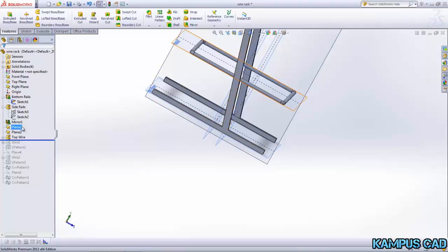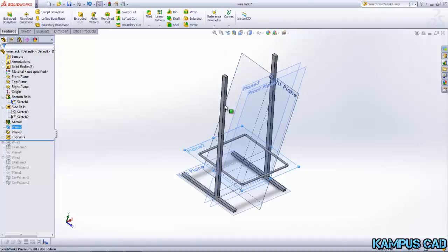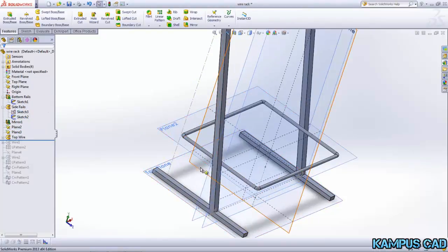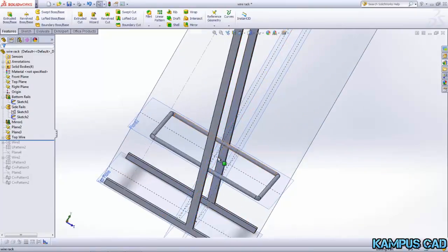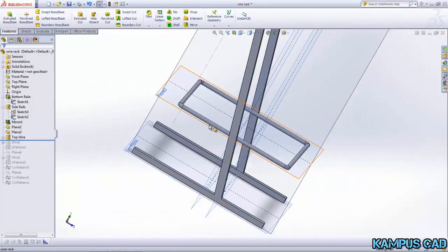And how I created those planes actually is I left behind some reference geometry. Let me make sure that trajectory is on. So my other sketch, I knew where I wanted to be at, so I left a point there. So I have this plane here, plane 2 and plane 3, intersecting that point. So instead of using a dimension to know how high up I wanted to go or how far over, I just left that point in my other sketch.